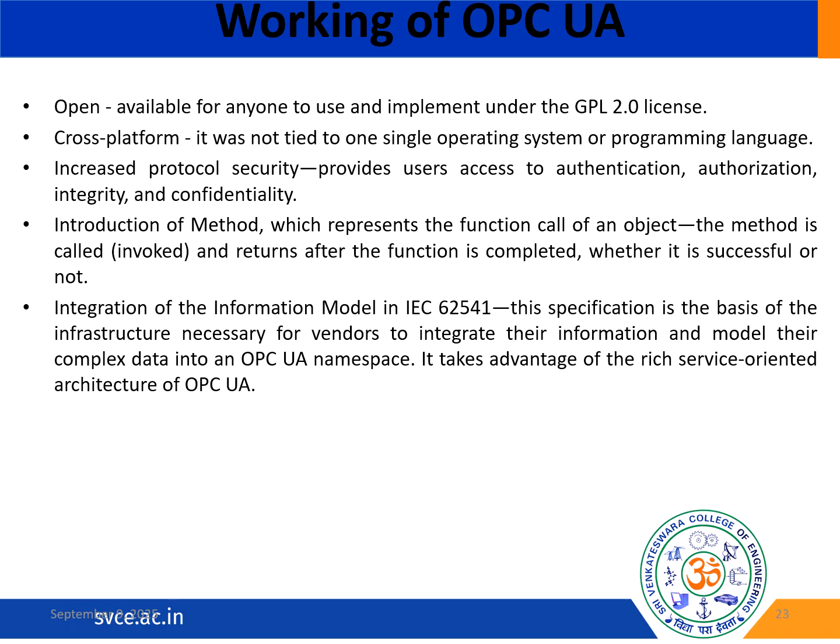To overcome the drawbacks of OPC DA, the OPC Foundation developed OPC UA, which is significantly different from its predecessor. The goal was to move away from mainly using Windows DCOM to better meet industrial automation's evolving needs.